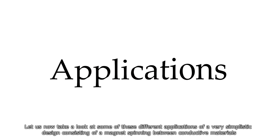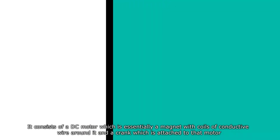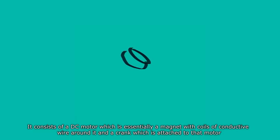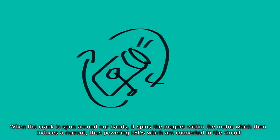Let us now take a look at some of these different applications of a very simplistic design consisting of a magnet spinning between conductive materials. Firstly, we have the classic hand crank flashlight that many of us may have seen sometime growing up, whether going camping or just looking around the basement or attic. It consists of a DC motor, which is essentially a magnet with coils of conductive wire around it, and a crank which is attached to that motor. When the crank is spun around by our hands, it spins the magnet within the motor, which then induces a current, thus powering LEDs which are connected in the circuit.